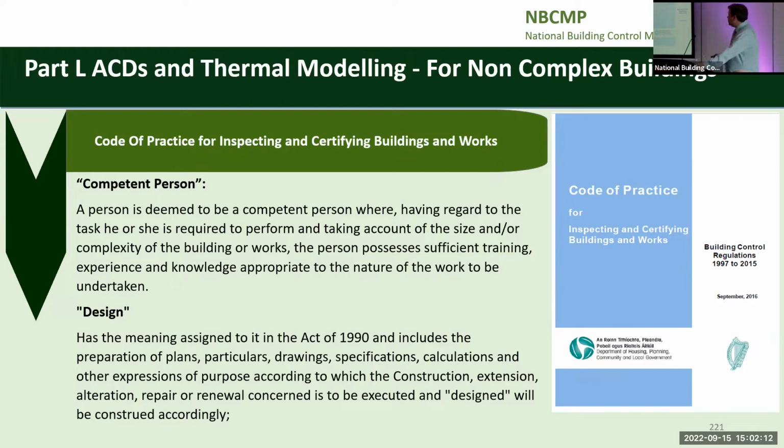The designer has a role in it too, under the Building Control Act as well: the preparation of plans, particulars, drawings, specifications, calculations, and other expressions for the purpose of the construction, extension, alteration, repair, or renewal concerned in the execution of the design to be constructed accordingly. So the designer here has to put all this information together, has to be talking to the thermal modeler, has to be making sure that his key junctions are in compliance with the ACDs if he's using the ACDs. And if he's not using the ACDs, has to get his FRSI calculation and use the default.